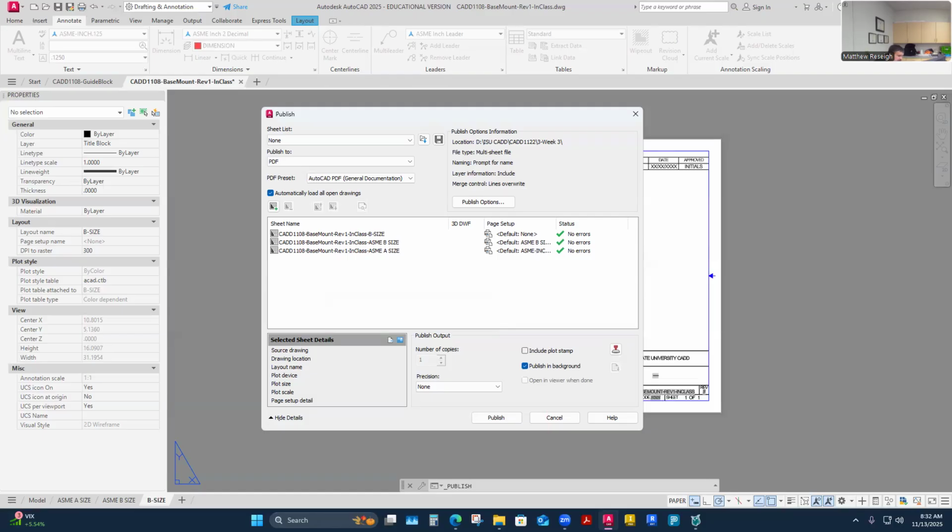But it does vary, and there's a lot of online forum discussion about how companies either do the revisions only, or they move the whole print pack up to Rev1, not just the individual sheets that were revised. So it varies. My common practice was we revved the entire print set, so that all pages carried the most current, latest revision number.